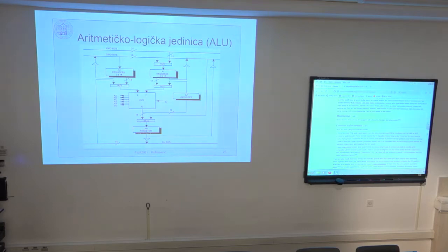So the ALU is, I would say, maybe the simplest one. As I said, it has dedicated input registers for the X branch and for the Y branch. Actually, I have here 2 registers, AX0 and AX1, 16 bits wide.